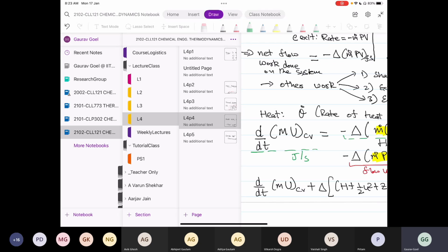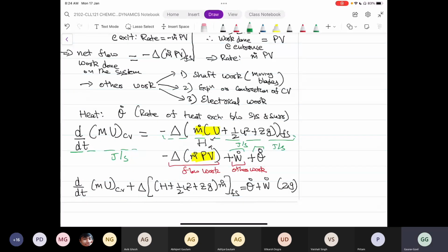But again, that P would be affected by, like we call, the Bernoulli equation. Here we ignore friction, and I take 2 points in a flow system. The pressure and velocities are related at those 2 points. So along a streamline, pressure and velocities will be related to each other by the Bernoulli equation if you ignore the friction effects, that means fluid viscosity, in pipe flow. But yes, P here is static pressure, but it will depend on the velocity indirectly.